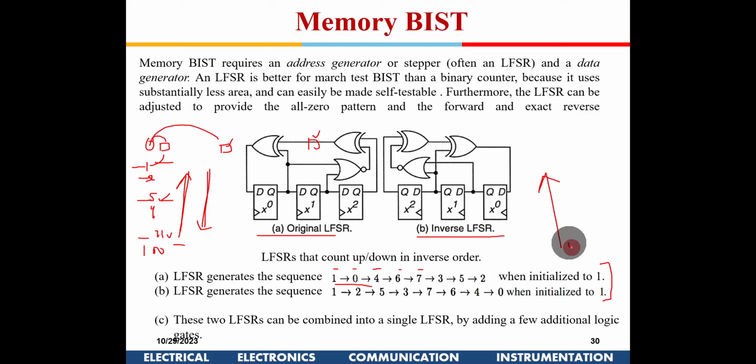Although it is a march test, normally if you are doing a single march, then the address will go 0, 1, 2, 3, 4, right? Now if you remember from our memory design classes, I test this cell, there are 5 cells here which I need to test. So I'll put some data into all these 4. Again, in parallel, because the read write operation takes more time, I will have a different cell out here. I will put the same data out here and do the operation in this cell and this cell, and hence this is not sequential, jumping from this address to this address. Although it is a march only, it is a mix and match of doing this march test at different locations, and hence this address pattern will look something like this.